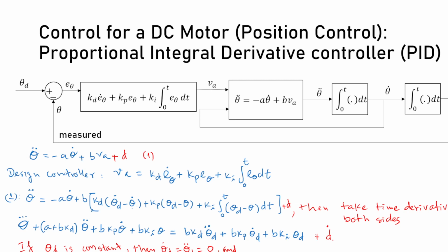And if your motor has a brake, let's say you impose a constant brake, and you just use a PD controller, the brake will make the performance poor. I mean, the rotor cannot rotate to the desired theta d. It just approaches and then stops. It does not asymptotically approach zero error, but has some certain error, which is far from zero.